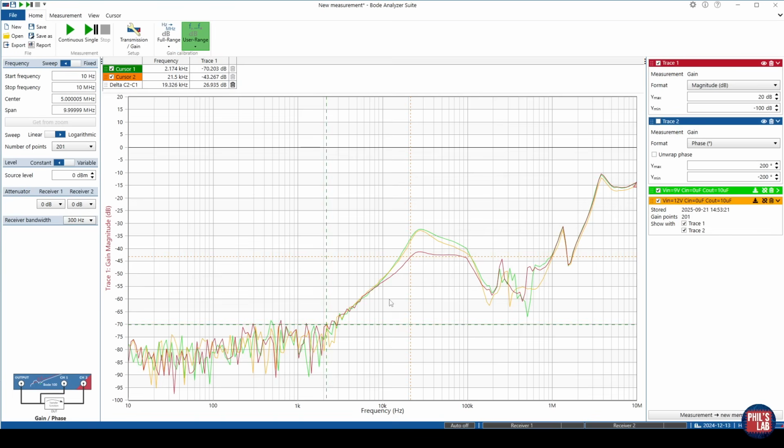But in the mid-band, where our aluminium electrolytic capacitor is effective, a fairly low impedance, that's typically around the 10 to 50 to 100 kilohertz range, and that's why we get a dampening and a slightly better power supply rejection performance around that band simply by adding more external capacitance to the output.